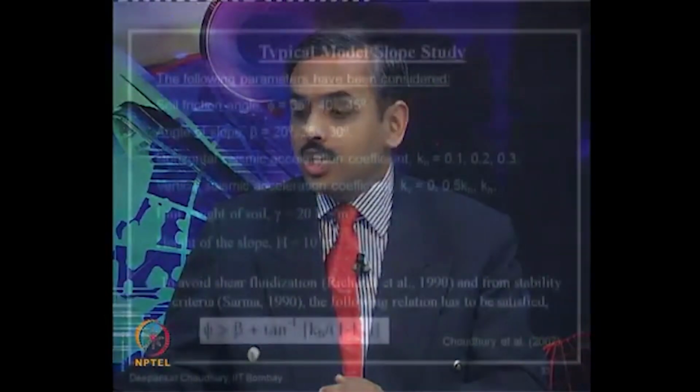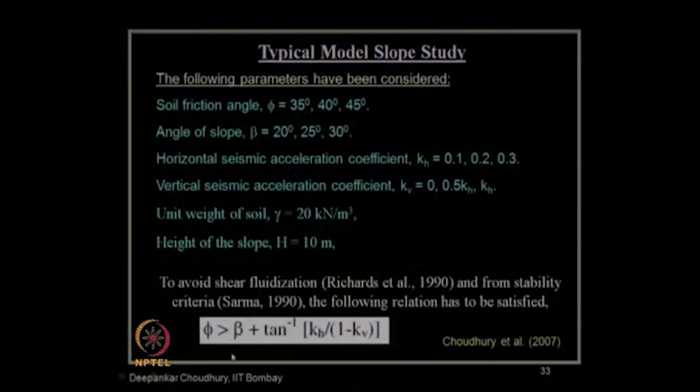In all these cases, even when we are considering the dry soil case, you need to consider whether the soil material itself is stable under that seismic condition or not. Because at very high value of shaking, the soil itself will start flowing like a fluid, though there is no presence of water. Clear?